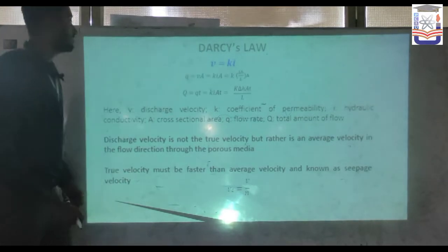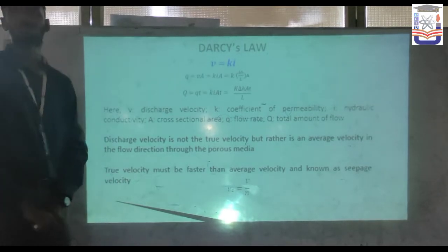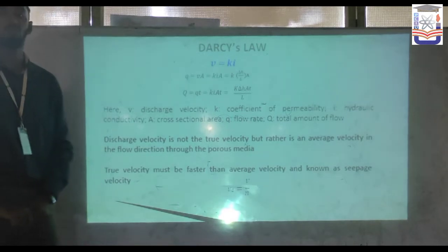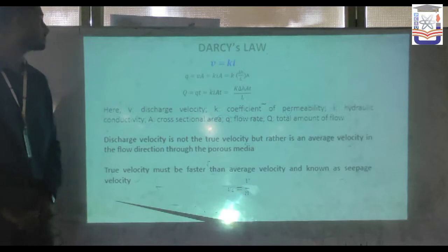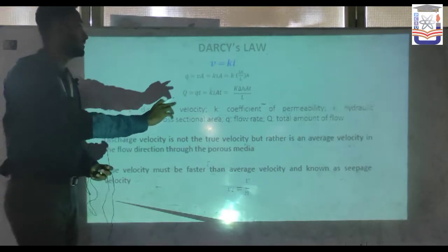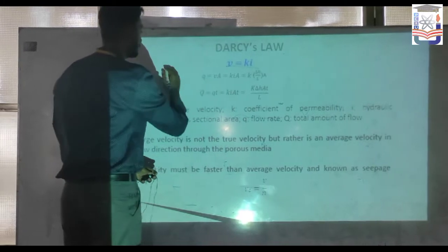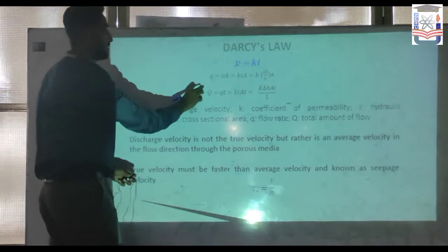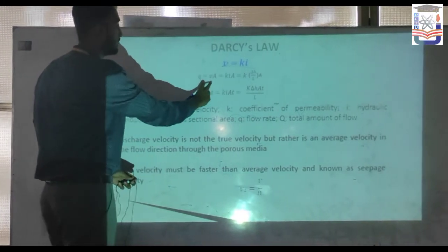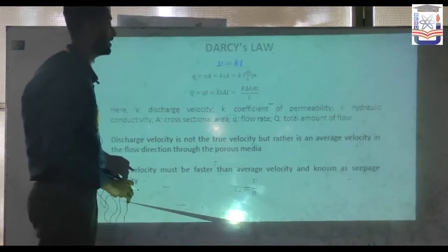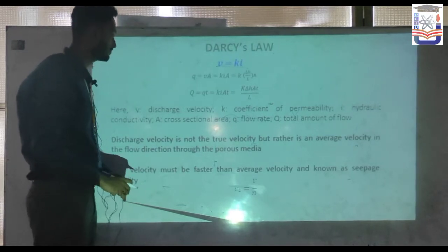Today I am discussing Darcy's law. What is Darcy's law? Darcy's law is an equation that describes the flow of fluid through a porous medium. The main equation is V equals K i. Then we find Q: Q equals V A equals K i A equals K times delta H divided by L times A.